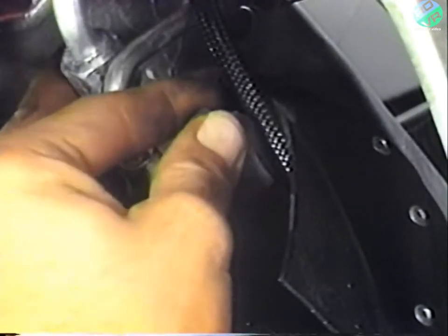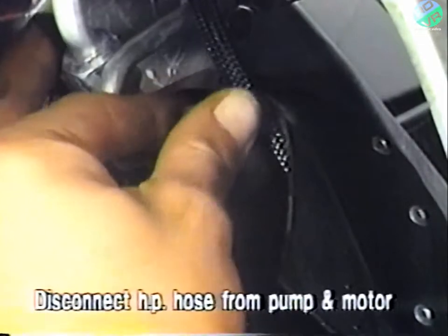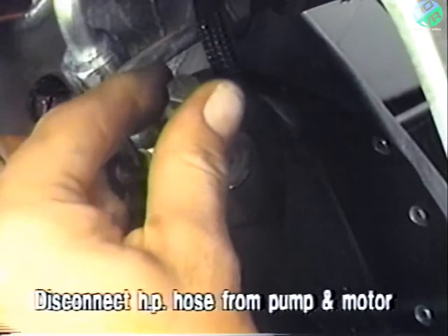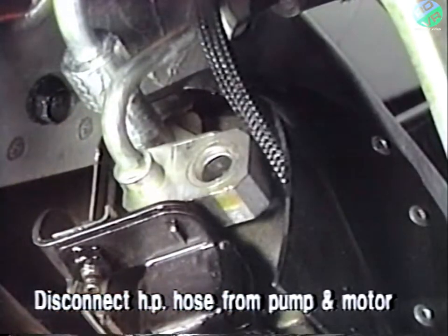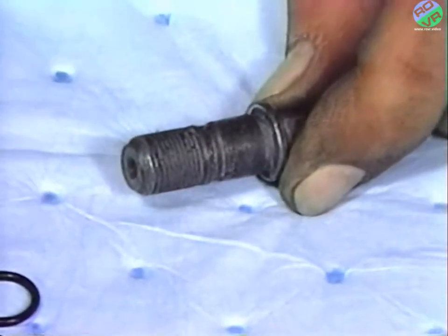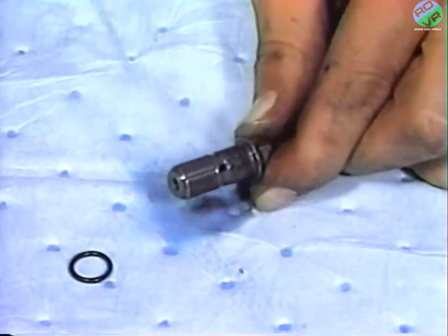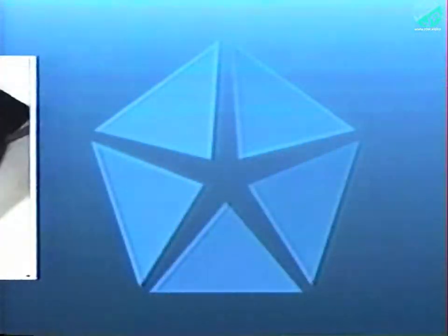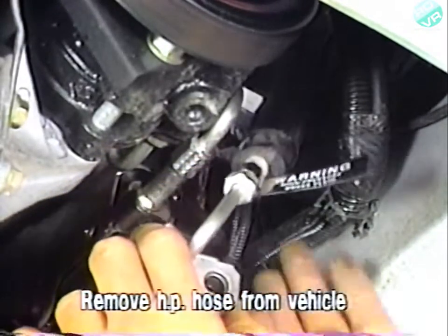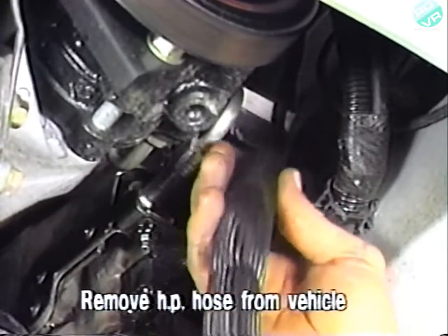Now, raise the vehicle on a hoist and from under the vehicle, disconnect the pump end of the high-pressure hose from the pump and motor assembly by removing the banjo bolt. Remove the O-ring, and clean and save the bolt. Again, being careful not to disturb the pump end of the other low-pressure hose, remove the high-pressure hose from the vehicle.